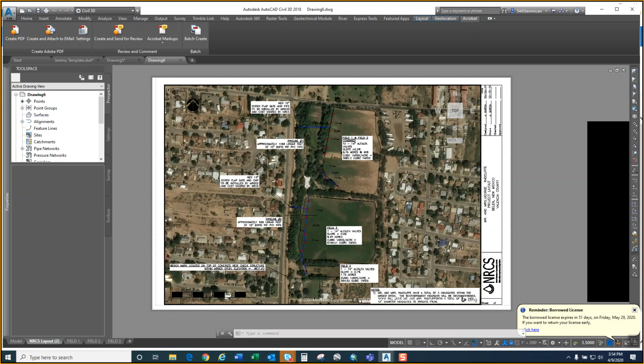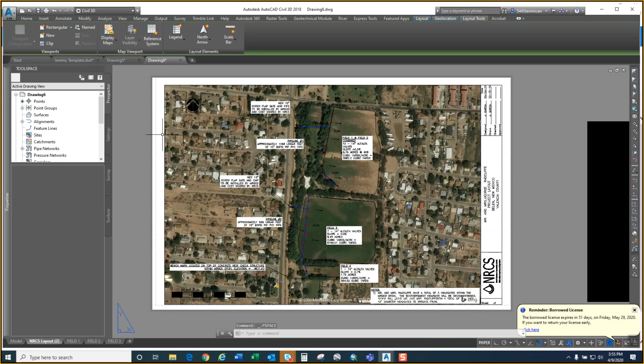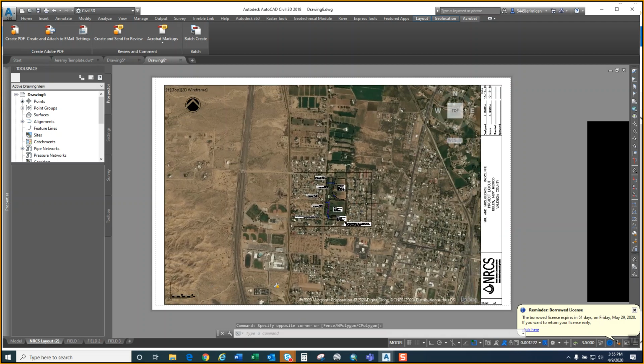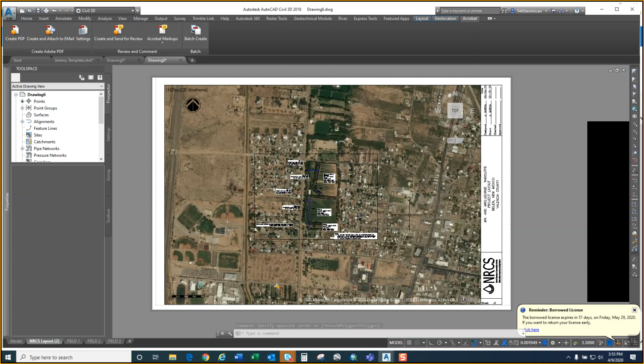So now I'm ready to start a new layout for a new drawing. I have the template that I need. As far as AutoCAD, you have paper space, which I'm currently in. As soon as I double click in the viewport, that's what this black line is, the viewport. When you double click it and the line turns bold around it, you're in model space. So I can zoom in and zoom out of model space as I deem fit. As soon as I double click out of model space,